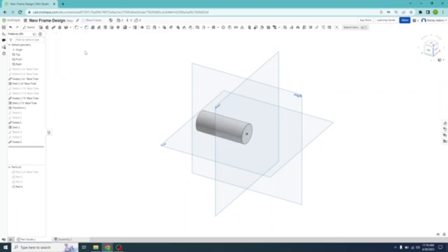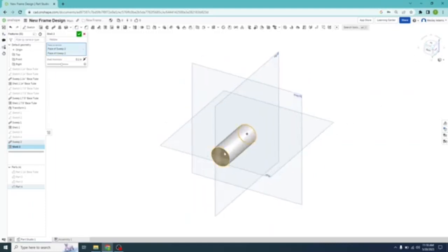Close that out. And you can see how we're starting to get repetition with a lot of the skills that we've already used. We're going to left click on the shell, so the outer part of the circle, left click. Let's scroll around to the other side, same thing, opposite side, but we need to set our dimensions here, 0.24, we know that'll work. It's going to be the thickness we need and the diameter of the hole that we'll need to slide our part in, and then close that out.